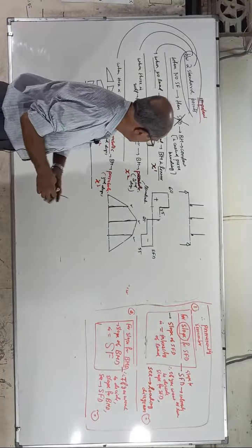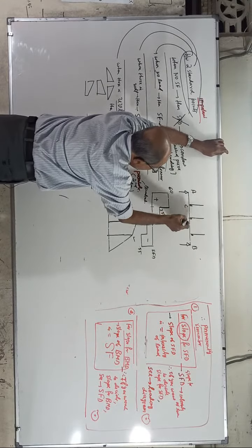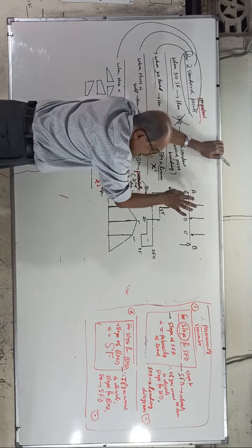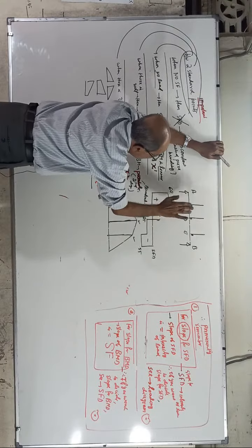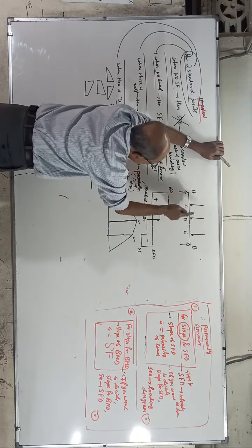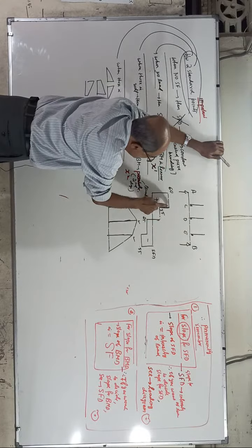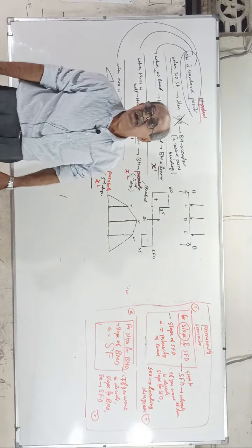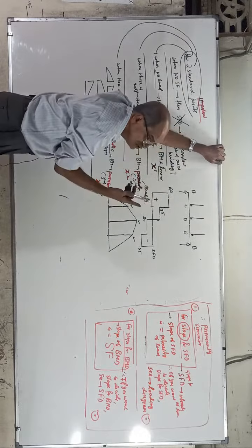Okay, see. Now this is a bending moment diagram. I will name the points A, B, C, D, E. Between A and C there is no loading. C has a point load, that is not important. Between C and D also no loading. Between D and E also no loading. E and B also no loading. So between A and C, C and D, D and E, E and B, shear force will be constant, parallel to the baseline, or slope equal to 0. Correct? The rate of change of shear force is the intensity of load, no intensity, so 0. For a horizontal line, slope equal to 0.